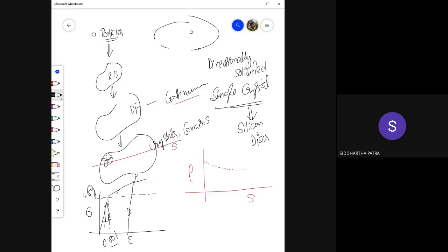Elastic deformation always happens every time there is a change in stress, and the change in stress is only due to elastic strain. If there are only plastic strain, there would be no change in stress. You must have seen this curve called elastic perfectly plastic. Being perfectly plastic means when it starts deforming in plasticity, there is no further elastic deformation happening.